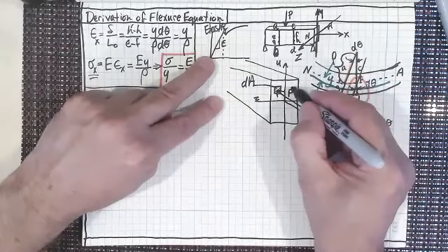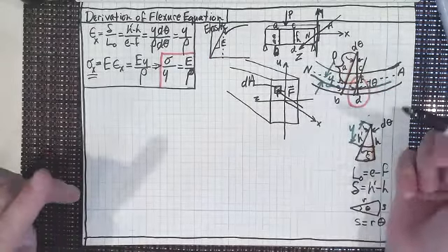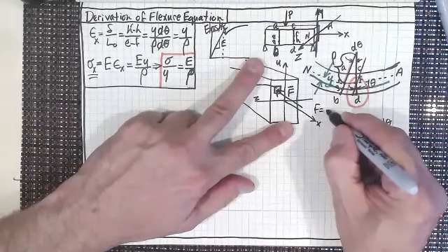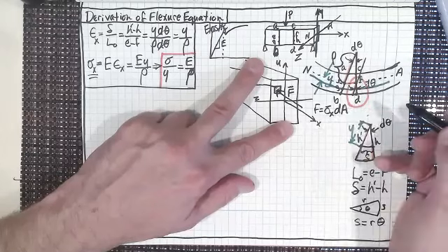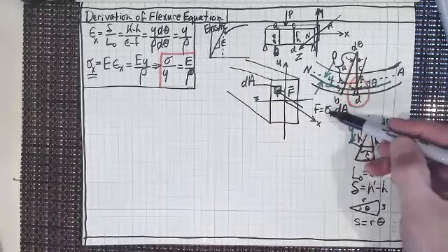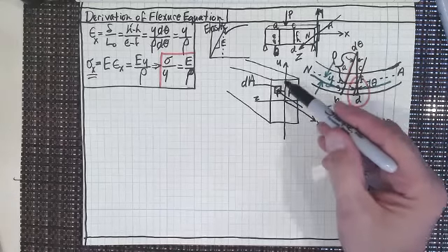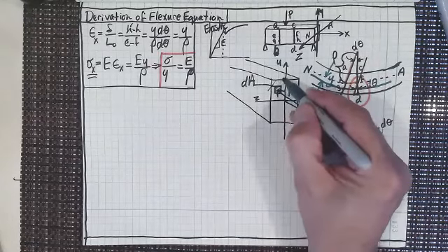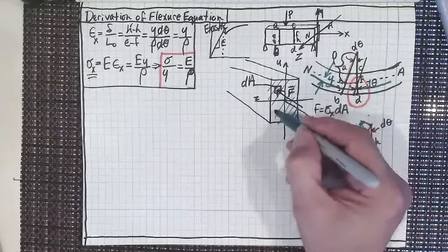And if I've got a force that's pushing in that direction, what is that force? Well, isn't the force just equal to the stress times the cross-sectional area? In fact, couldn't we just find out what it is for that little small cross-sectional area and then integrate it across the entire cross-section of the beam that we have? I'll just cross-section that out real quick, make it look nice.